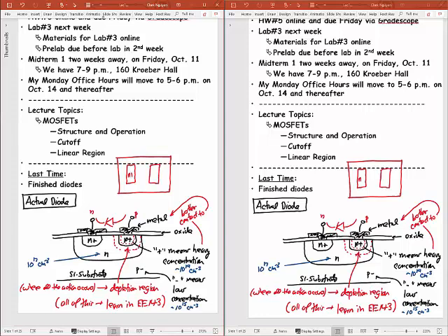So I'll have my N plus part there, my P plus part there, and my N part would be right here. That's my diode there in the top view, or what I can call a layout view, when you actually implement this, because that's what you're going to lay out when you're trying to make this diode.